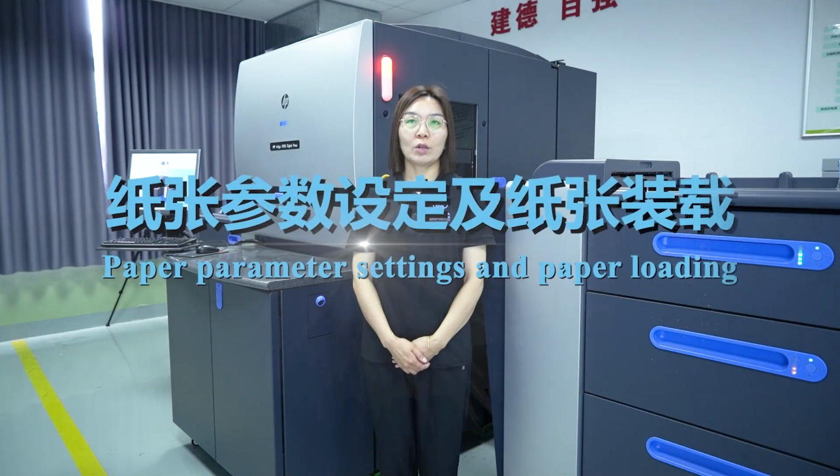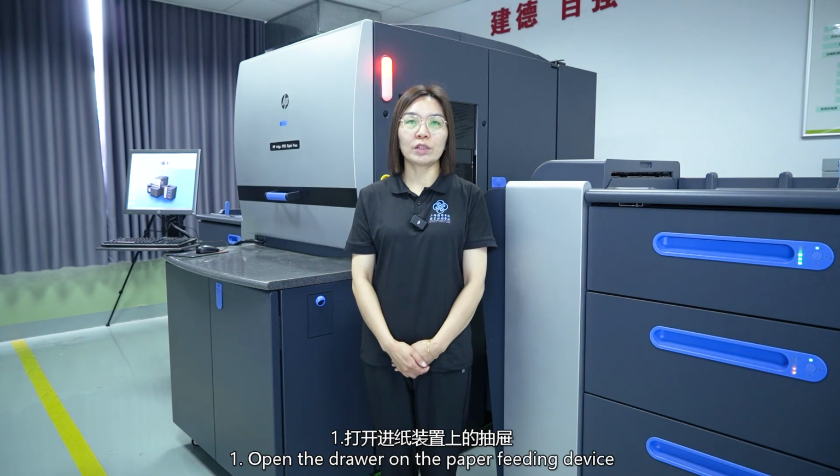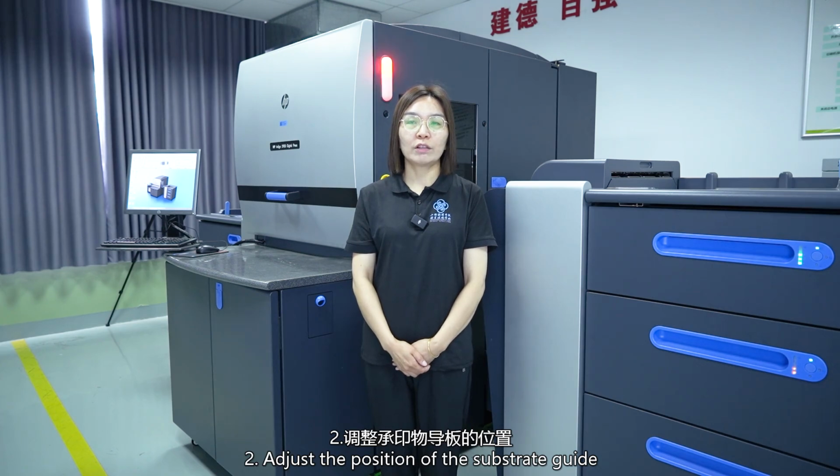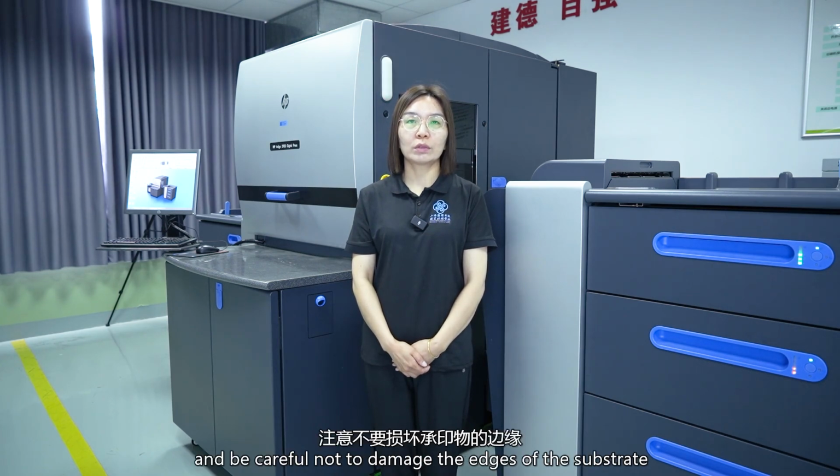Paper parameter settings and paper loading. To place the substrate, please follow these steps. Open the drawer on the paper feeding device and put in a small amount of substrate. Adjust the position of the substrate guide and be careful not to damage the edges of the substrate.